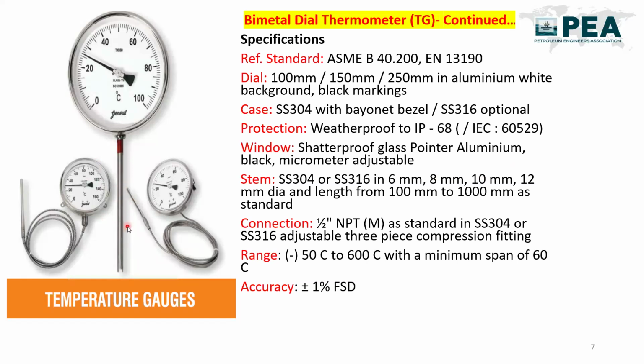Thermowell dimension will depend upon the various process fluids. So in that case you will have to select the stem diameter as per the thermowell dimension. We do not select the thermowell as per this dimension; we select this dimension as per the thermowell. Correct. Again the same thing applies to the length of the stem. The length of the stem will depend upon the length of the thermowell, so we will discuss that during the thermowell discussion.